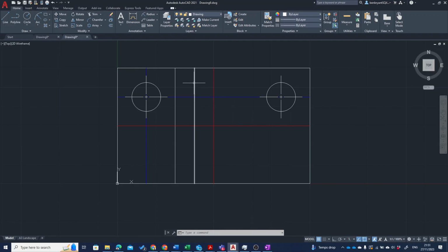You could have actually mirrored those 2 at the same time as well. So what I'm going to do is choose those both, go back to mirror, and click the center point again. If you go down, you can also use the same latch, as long as it's on the same line. Keep the original shape, no. So now I'm going to choose those 2 again, and these 2.